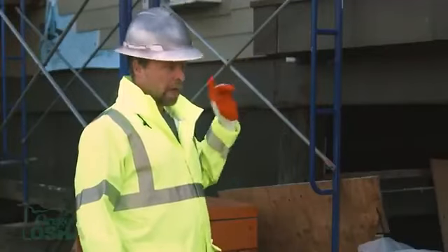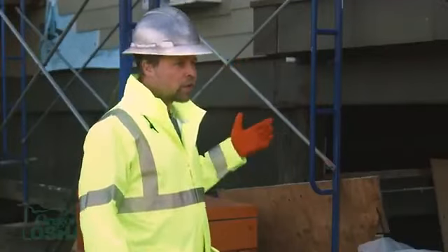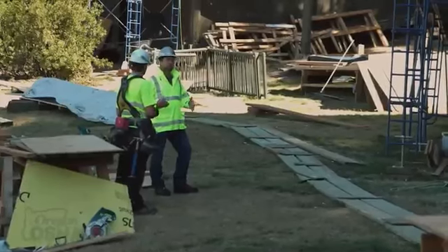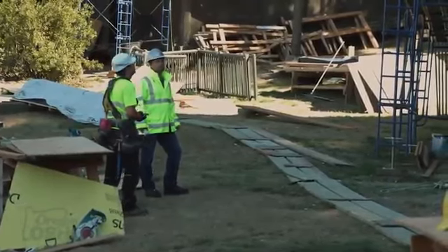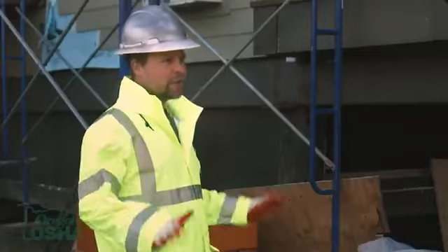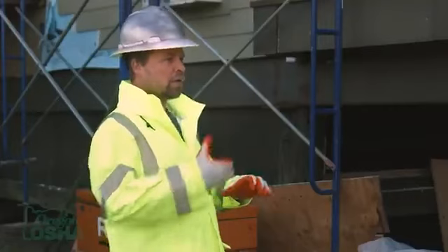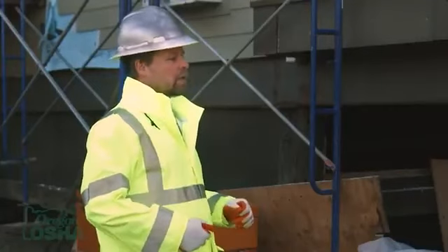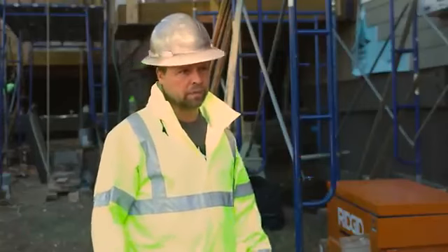That's what they tell all the guys too. If you have a rope hanging from the roof, you have to go make sure that's installed. What if somebody just left it? Proper procedure is to make sure it's hooked up properly, test it, and talk to your supervisor. The supervisor has to verify it so everybody knows, okay, green light, you can go ahead and use it. If it's not set up, everything is worthless. It starts from the top: make sure the anchor is properly attached, make sure the rope is properly attached. It could have been an old building or it could have been rusted out, so maybe there was a time to replace it.